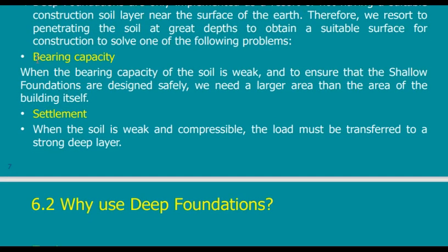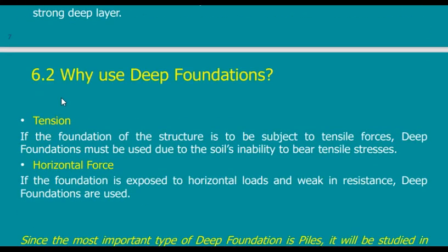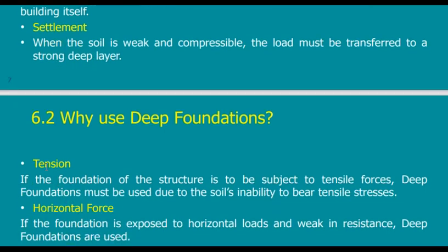First problem is bearing capacity. If I use the bearing capacity equation and I find that the bearing capacity of the soil is not adequate, or I use the settlement equation, I check the settlement of the footing and I find, say, a 20 centimeter settlement, it's not possible. These are related to soil; the next are related to loads: tension and horizontal load.